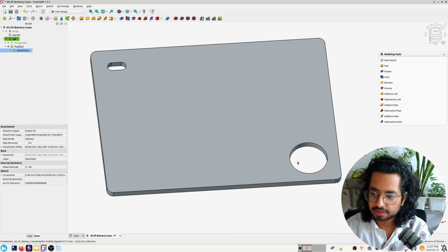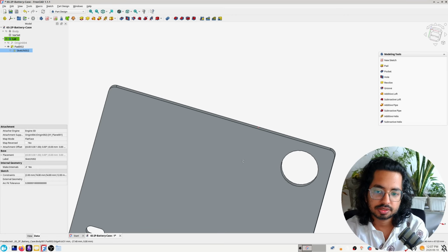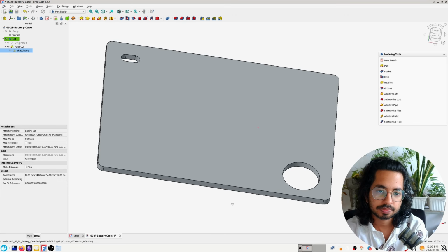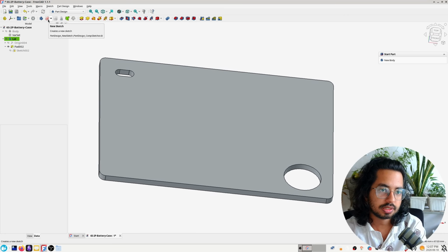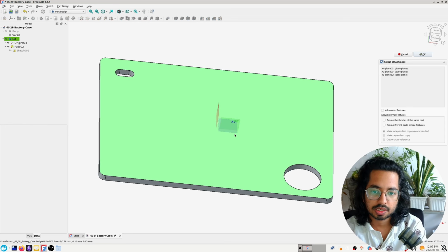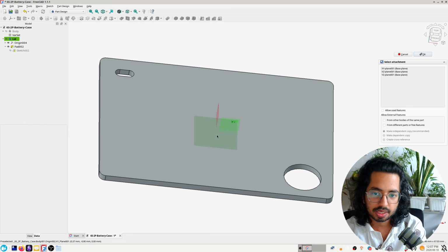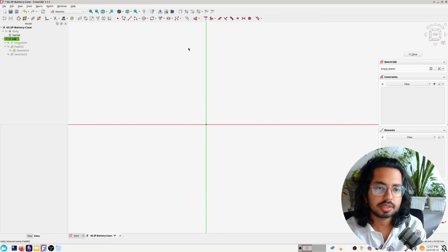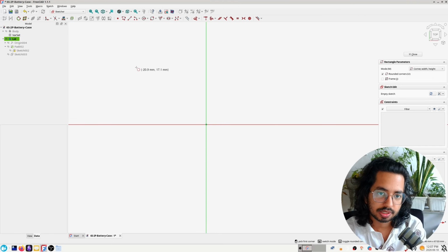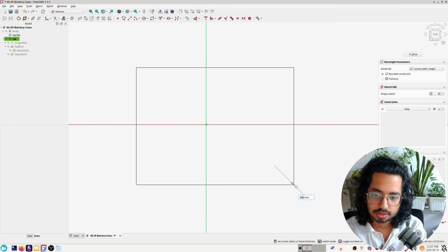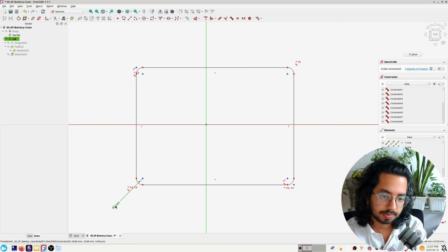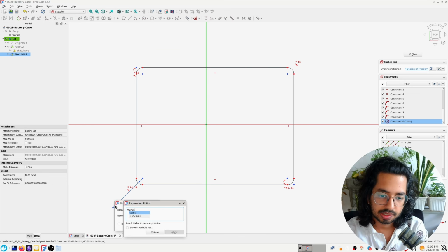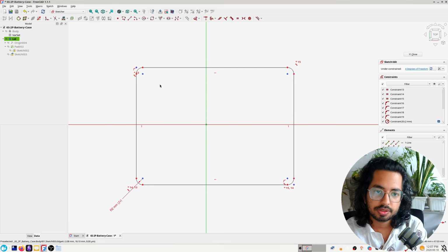Now let's make the inner wall. That is going to be pretty simple too. Click on new sketch, and we want it to be on XY as well. I will hide this since we don't need it, and again come back and use the rounded rectangle. 2 mm, this will be replaced. Double click, varset, fillet. Now we need to put the length.